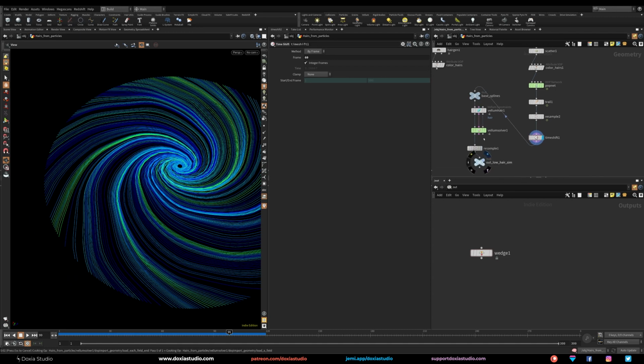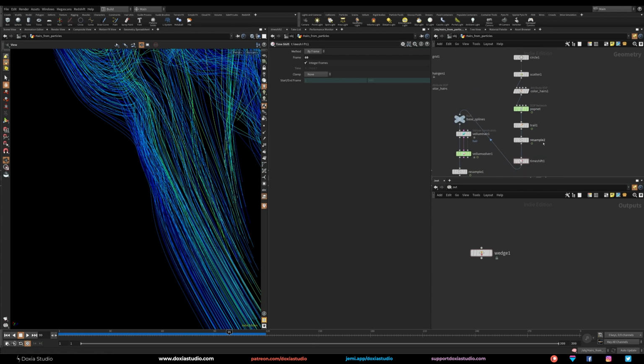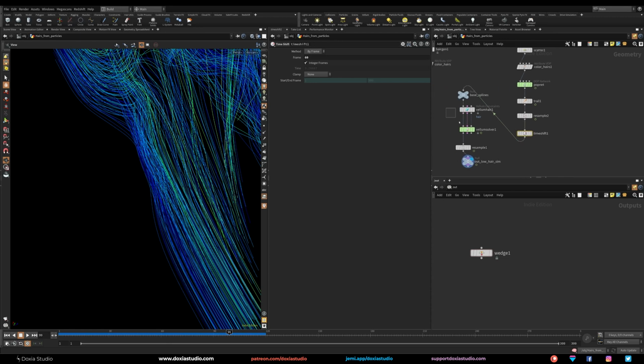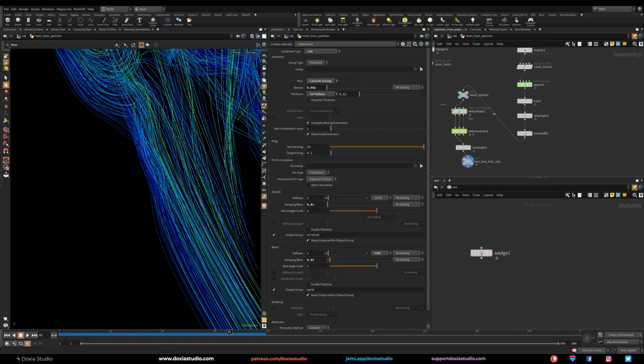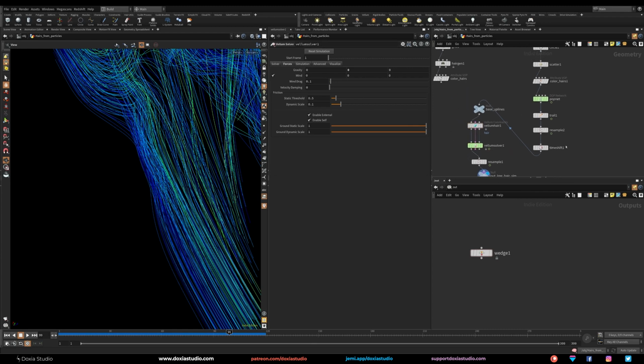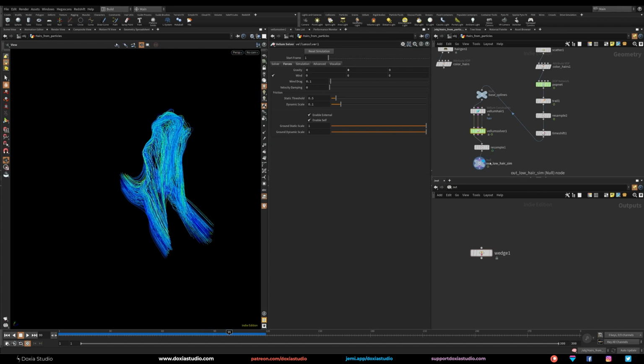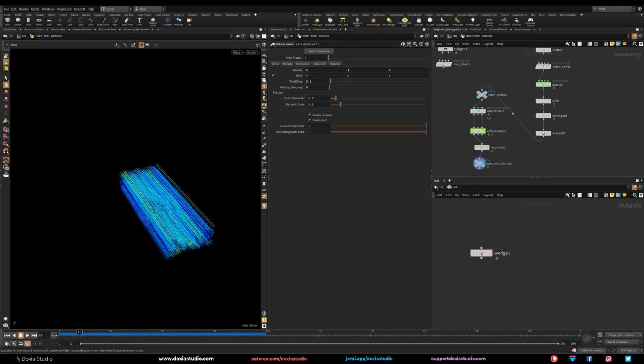So now let's go here and everything will work for us. Oops, now it's processing. I hope this will work. Let's see. So now I've used PopNet to create my splines with particles. Then I stopped the particles to have the points in place, and then transform those primitives into hairs, and then use the Vellum solver. As you can see, they are behaving like I want. There's something wrong. What happened here?